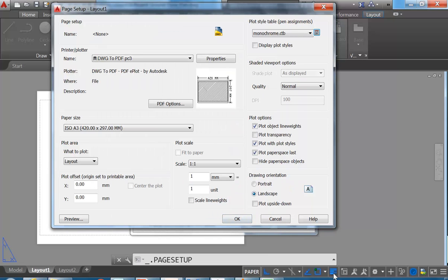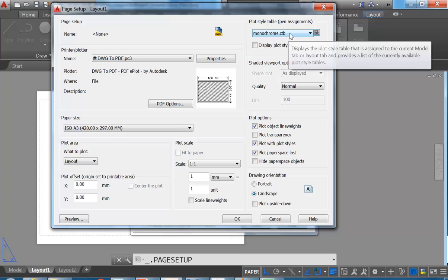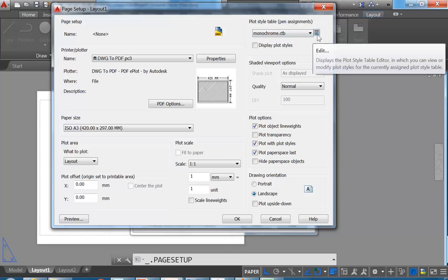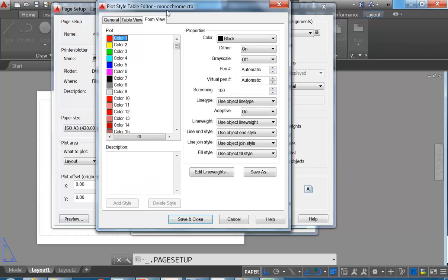But if you like using this line weight option down here, that won't do anything. It doesn't recognise the things you set in the plot style table. That's another reason I like doing it by layer. It is the way that Autodesk have been trying to get everyone to use this approach for years, and there's an even newer approach using a different kind of file.